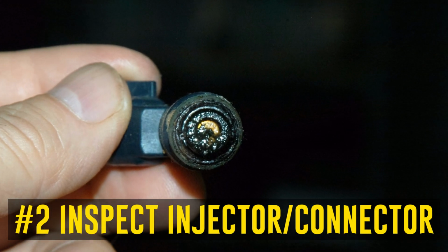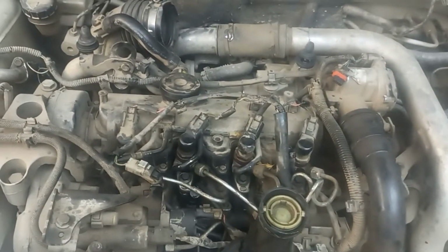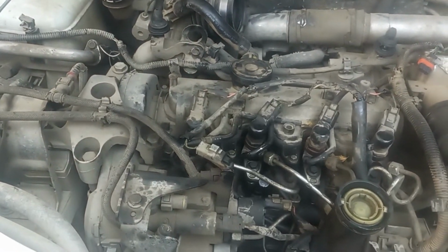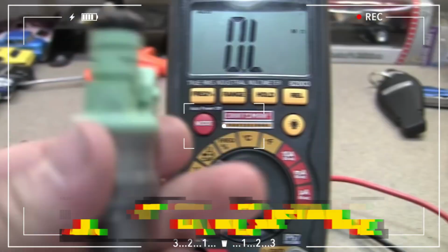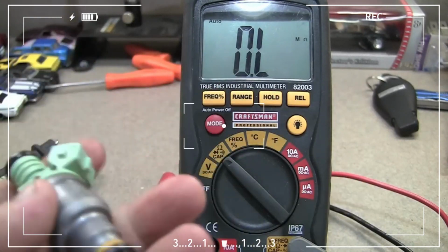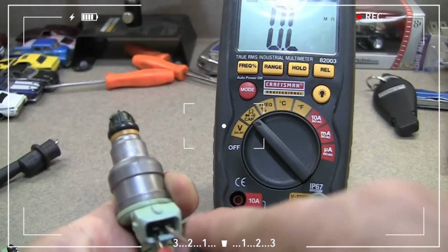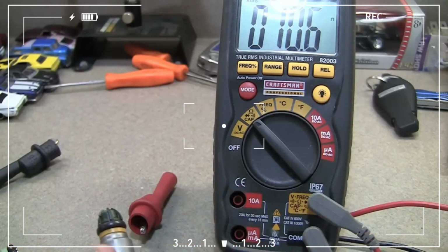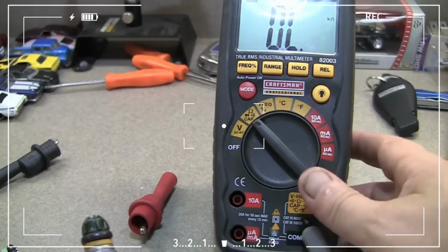Inspect injector and connector. Start the diagnostic procedure by visually inspecting the number 3 fuel injector and associated connector on your engine. If at all possible, any such damage ought to be fixed before moving further. Replace any and all damaged parts as needed. Check resistance. A resistance test ought to be carried out if an inspection reveals no damage. To measure the resistance across the solenoid of the number 3 injector, use a digital multimeter. It is recommended that you compare these readings to the manufacturer's specifications for your car. If these readings are abnormal, the offending injector needs to be changed.